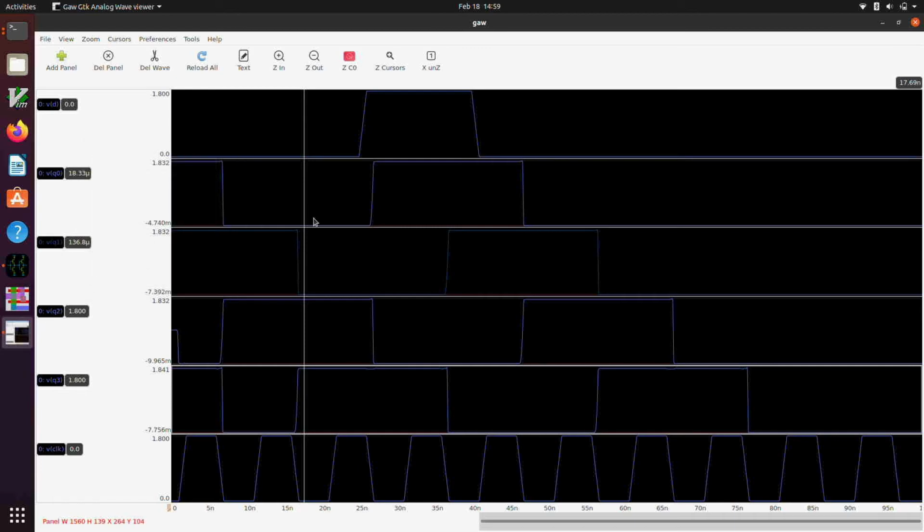So this is kind of what we might expect to see, right? When the pulse goes high, it doesn't propagate to the first Q output until the next falling edge of the clock, which it does, and then we don't shift that over until the next falling edge of the clock. So this pulse propagates to the next stage on the next falling edge of the clock, propagates to the next stage on the next falling edge of the clock, and then finally it arrives at Q3 on the next falling edge of the clock. So this is all good.